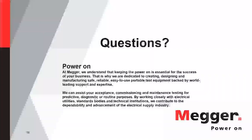As you're starting to get over 5%, I would say rebound maybe half that. You can over travel some. As you're starting to rebound, it's a problem as well, especially for vacuum circuit breakers, because now those contacts are touching, and if you rebound, you can have quite an arc there.